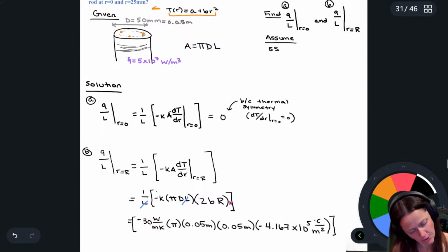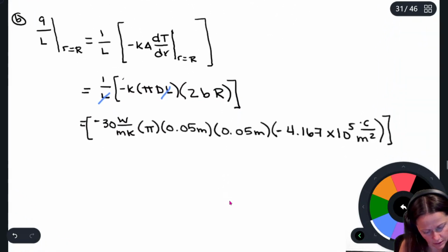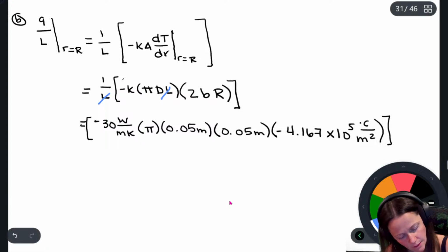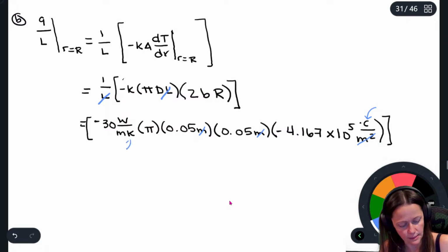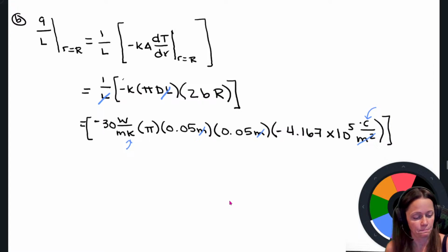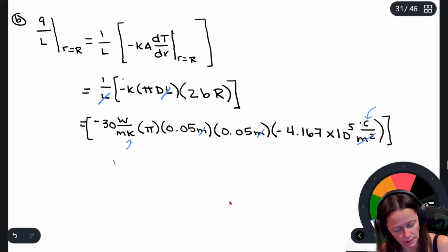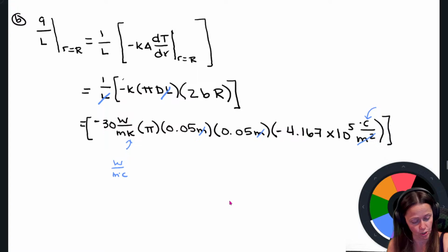All right, so just look at the units that I'm going to get here. So meter squared, meter squared. Yes, I know I've got a Celsius up here and a Celsius down here. It does not matter because I could put this in watts per meter degree Celsius, and remember that wouldn't change because they're defining it per unit degree change.